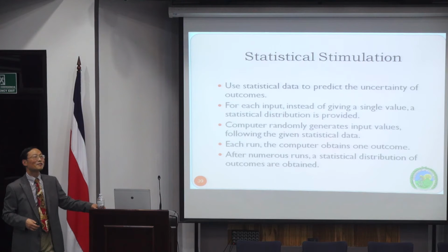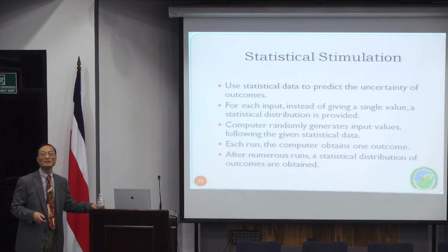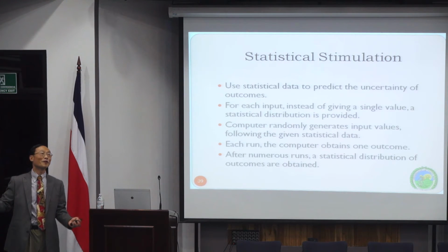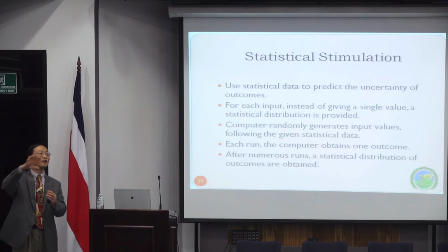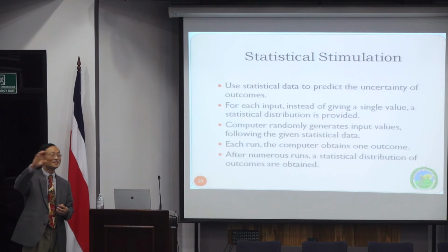Traditionally, when we do an estimate, for a civil engineer the easiest way is to talk about a construction schedule, like the CPM, critical path method. With CPM, you break the project down into activities, and each activity has logic links showing how the activities are related. After you do that, you assign the duration of each activity.